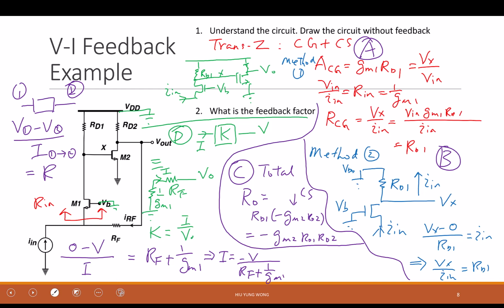What does it do as the output of the feedback? It is trying to track the current input by the feedback, so it is a source of current. Yeah, a good current source needs to have infinite impedance. So very lucky, everything is consistent. Just one resistor, I make it large, I fulfill that I'm a good voltage sensor and I am a good current source, right? And how about 1 over GM?